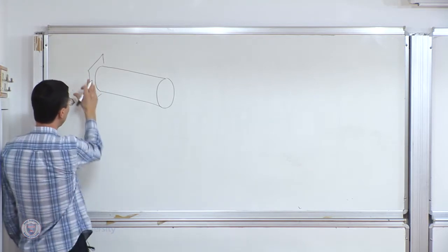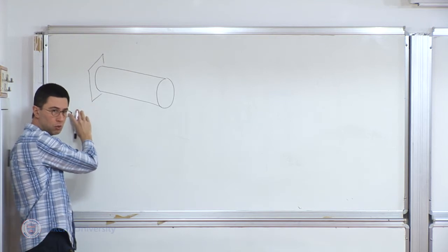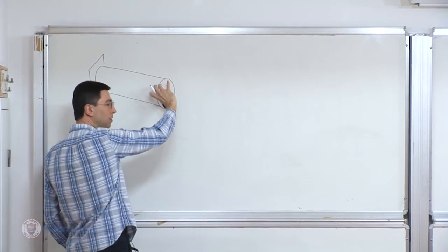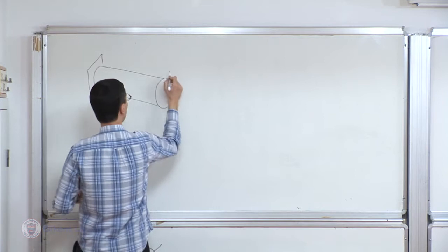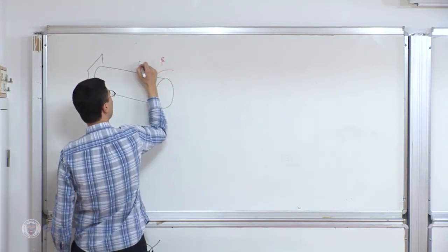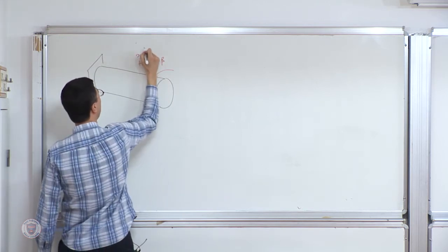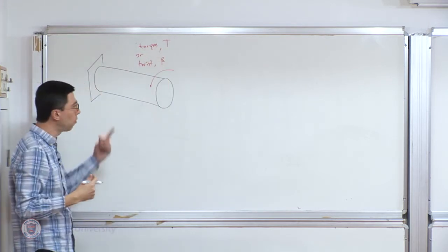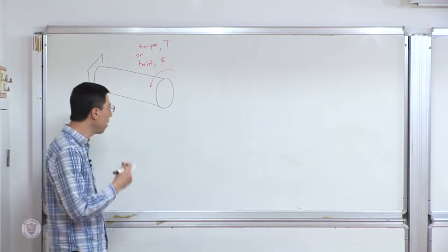But presently we have a cylinder, it's fixed at one end, there is no body force or force per unit volume, there is no acceleration. So it's a sort of a quasi-static thing. I'm going to twist the end. I'm just going to look at the solution for a given angle of twist, which could be a rotation through beta. That would be angle in radians. Or I could have a torque applied at the end, which was T. Okay, so that or the other one, it doesn't matter.